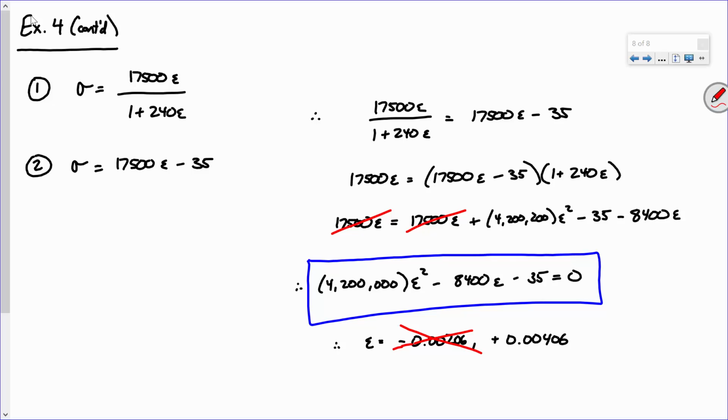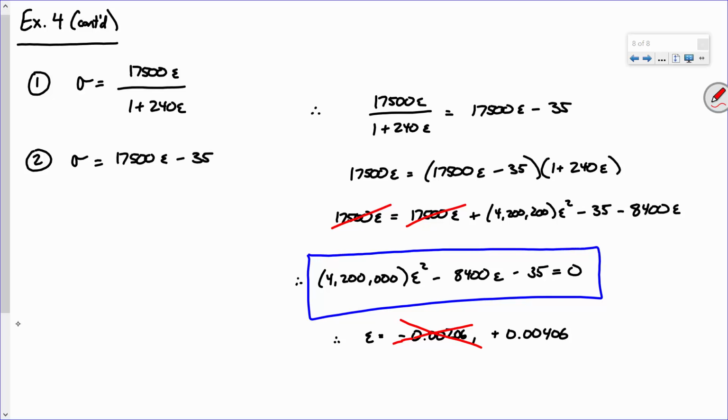all right, there we go. Is this our answer, though? No. Why? What are we calculating? We're calculating a 0.2% offset stress, right? Not a strain. Okay? We take this value and then plug it into one of these equations to get the strain. Does it matter which equation we plug it into? No, because this is where they intersect. It really doesn't matter. So for simplicity, which one you want to use, 1 or 2? 2.